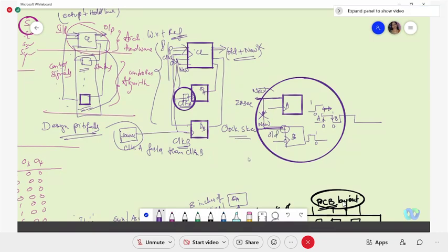Yes, ma'am, understood, ma'am. So in this duration, all the outputs that are defined will be a combination of this old and new. That is Q. So a natural remedy we suggest is either you make both positive trigger or negative trigger.